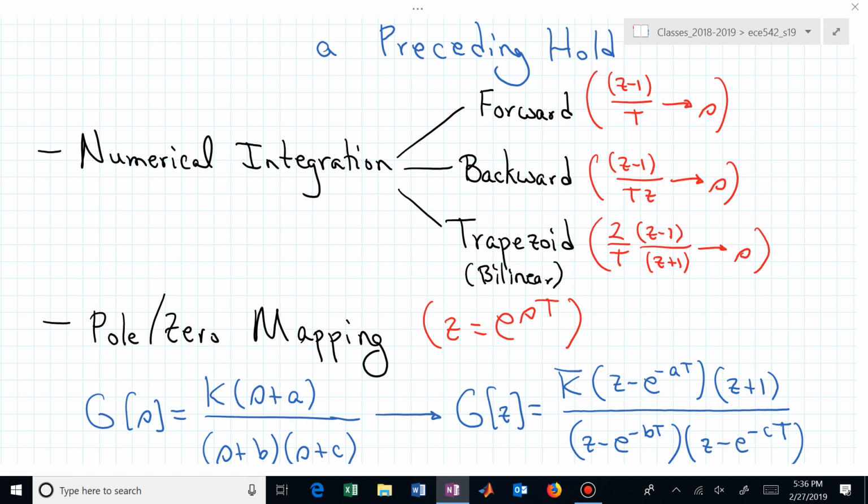If not, that's okay. It's not a hard concept. Zeros at infinity are really the number of, or how many fewer zeros you have, finite zeros, than you have poles. In this g of s expression, the order of the numerator is 1, the order of the denominator is 2. You have a pole zero excess of 1. And in fact, you have 1 zero at infinity.